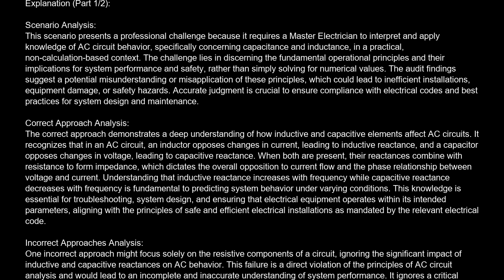Understanding that inductive reactance increases with frequency, while capacitive reactance decreases with frequency, is fundamental to predicting system behavior under varying conditions. This knowledge is essential for troubleshooting, system design, and ensuring that electrical equipment operates within its intended parameters, aligning with the principles of safe and efficient electrical installations as mandated by the relevant electrical code.